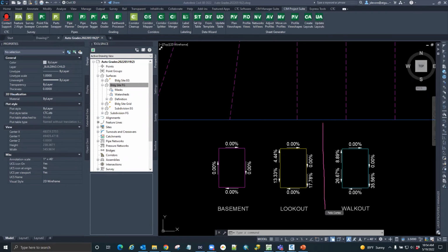So a typical workflow for this, real quick, you have your right of way here. You'd have to have something that ties to this. Usually I would use a feature line, set this side. One of the newer feature line tools is setting a relative elevation on this end, and then putting a label on this so you can see the grade. So let's say you want this to be 2% up, and then you would have to set this elevation again and then set all this. So the typical workflow is, there's a lot of work when the street starts changing.